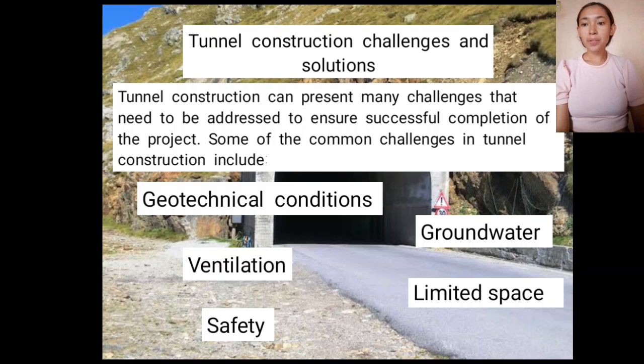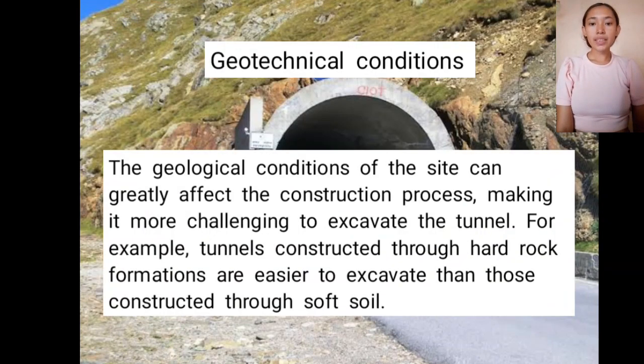Tunnel construction can present many challenges that need to be addressed to ensure successful completion of the project. Some of the common challenges in tunnel construction include geotechnical conditions, groundwater, ventilation, limited space, and safety. Geotechnical conditions. The geotechnical conditions of the site can greatly affect the construction process, making it more challenging to excavate the tunnel. For example, tunnels constructed through hard rock formations are easier to excavate than those constructed through soft soil.